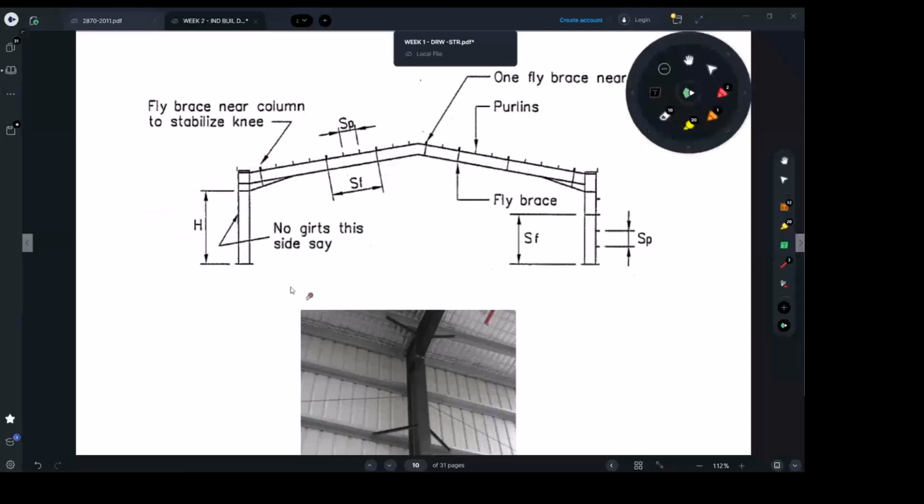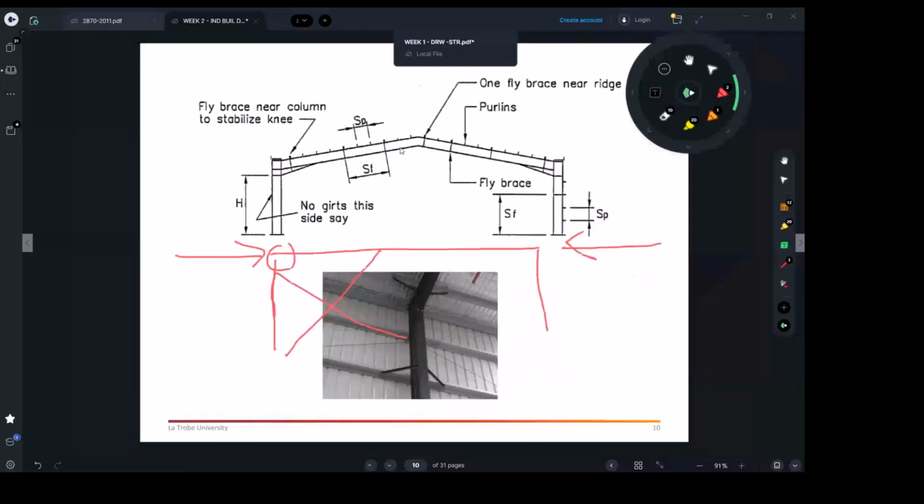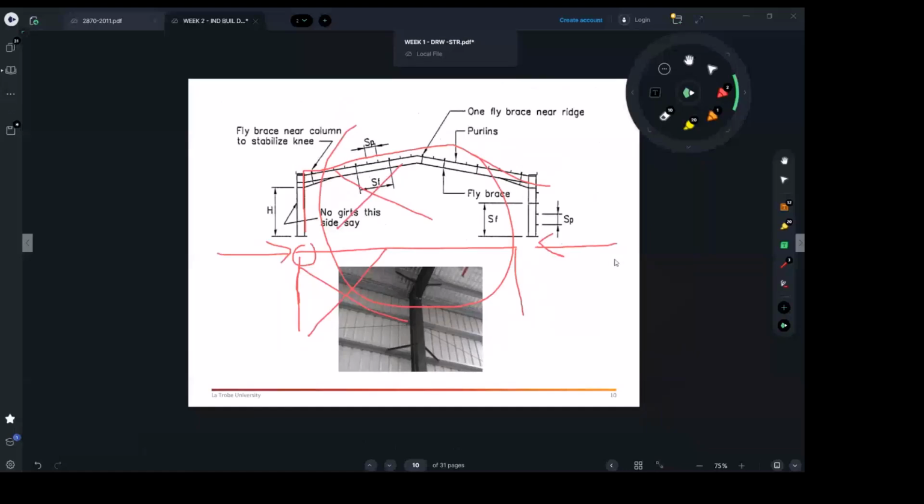What I mean with pin, it's another frame where you've got a beam like this. Let me just draw the beam. You've got just a beam like that, and just put it on two sticks with very simple, cheap pin connections, which can be just two bolts connecting each other. But this is going to fall down if you push it laterally this way or that way. It's just going to fall down. And in this case, yes, we need some bracing to put there. But in the buildings we're talking about, we cannot put bracing here. You're just going to have no access. So we have to use portal frames in the crosswise direction.